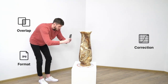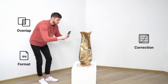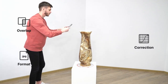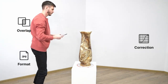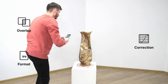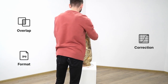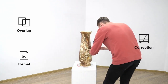Correction. So when it comes to correction of your pictures, you can actually do that. You can correct color or white balance, and you can do that in third-party software during post-processing. If you review your pictures and think they could use some improvement, feel free to modify them. But it is advisable to process all of the photos in the same manner. So please don't select just a couple of pictures, apply some filters, and leave the rest of the frames original. If you do apply some modifications, apply them to the entire photo shoot. And also, please avoid any geometrical transformations, resizing, and distortion corrections.